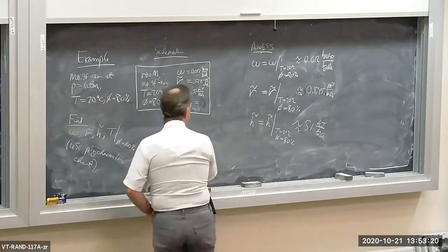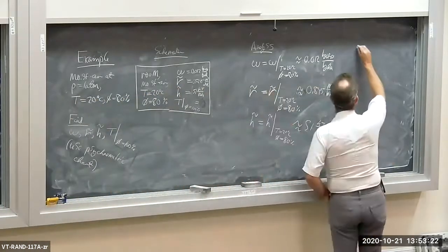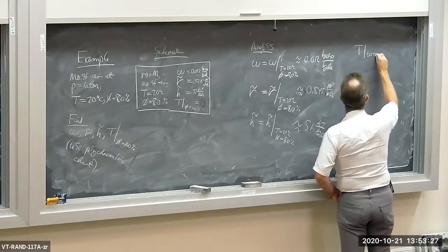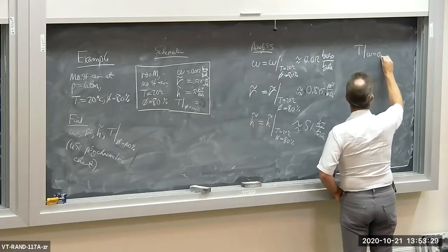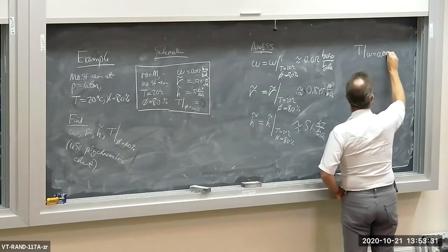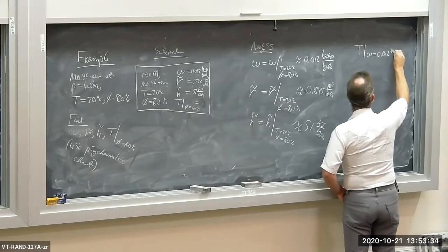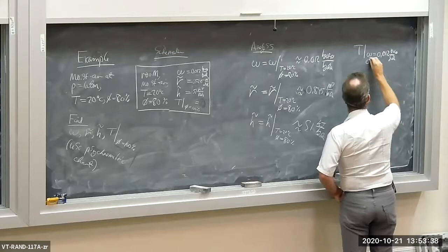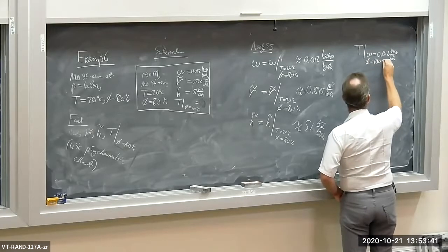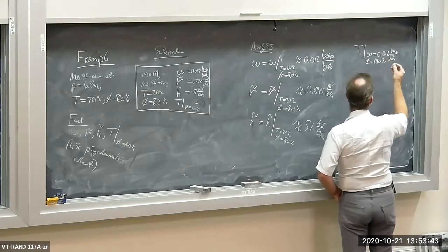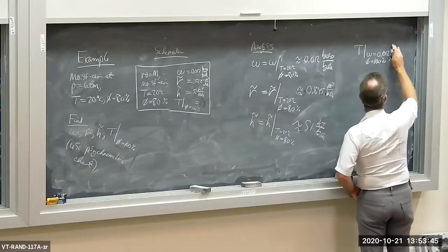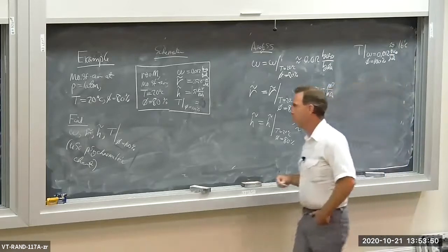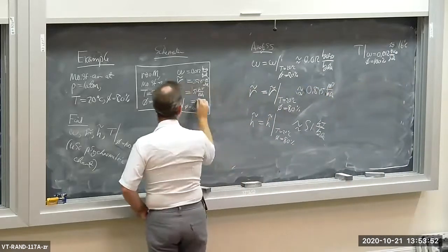Okay, so I'm going to write here the temperature at which omega equals 0.012 kilograms H2O per kilogram dry air and a relative humidity of 100%. So the air is saturated, is approximately equal to 16 degrees C. Okay? So I'll put 16 degrees C here.